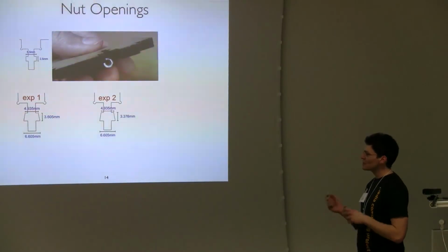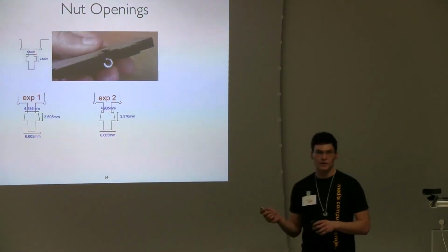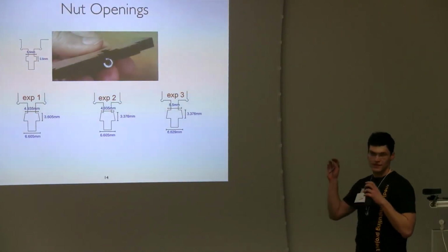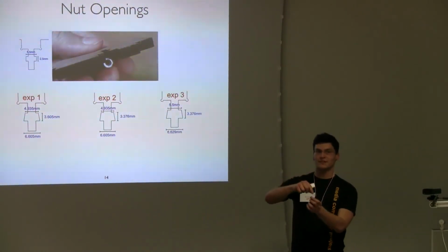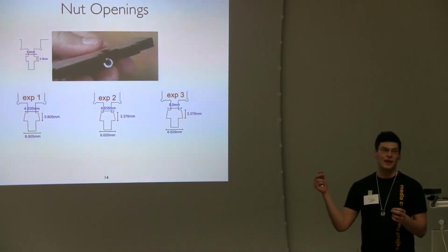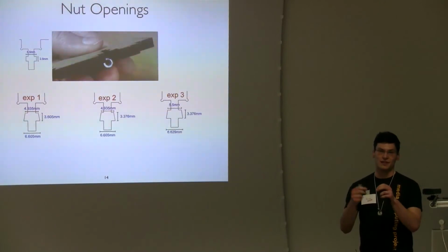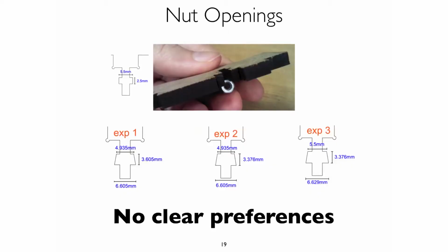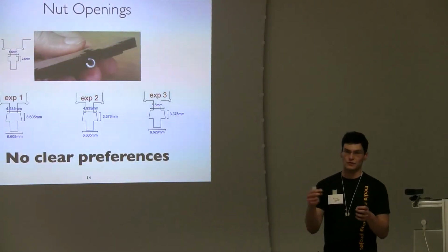We thought that if we changed the shape of the openings and gave it a trapezoid shape, the opening would be able to hold the nut. This is true, but unfortunately now you need to apply more force to insert the nut into it. We asked our users which design they prefer, and while they mentioned that the nut opening was holding the nut, they were unsatisfied due to the fact that they had to apply more force to insert it.